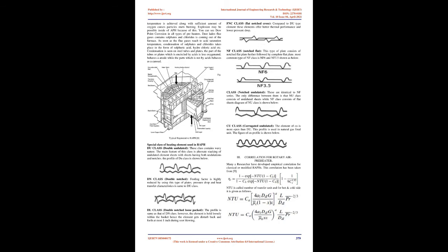The cold end flue gas temperature is drawn for acid dew point in APH, as complete burning of coal is done. Regenerative type. In that study, mainly two heating elements are used, either stationary or rotary. Wear and tear of the plates is reported as a primary problem, and high ash and silicon content is seen in dust-laden incoming flue gases.